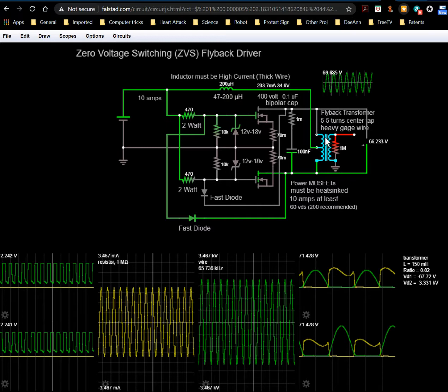The inductance will change. For example, if you're using this as an induction heater, whatever you put into that field will change the induction, the magnetic field in the circuit, and therefore change the inductance. So it'll affect the resonance. So the frequency will change depending on what you put in that coil. And if it were driving a flyback transformer for high voltage, again, if you're pulling an arc on the thing, that'll change the load on the transformer, which will change the inductance on this thing.